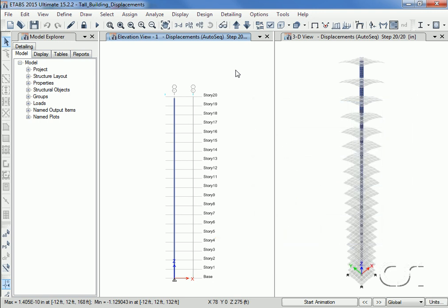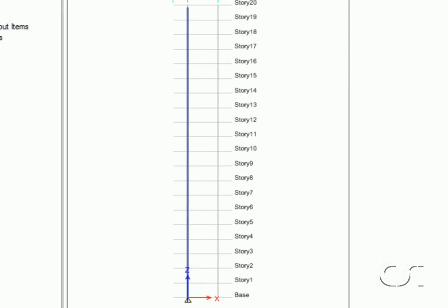Assuming that all of the floor loads are identical, the first story column has a load of 20 W and a length of 1 H. That is, it supports 20 stories of floors and has a length of 1 story. Because each column is poured such that it compensates for previous deflections, the top story column deflection will be equal to just its own deflection, and it has a load of 1 W and a length of 20 H.